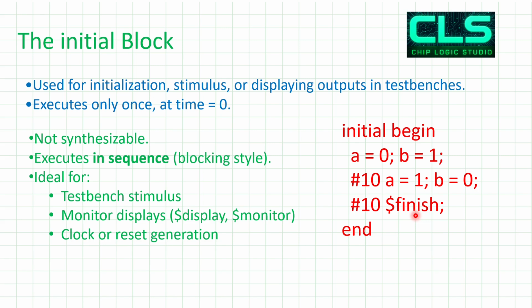After 10 nanoseconds there is no other $finish. So why would we write this in an always block? These are statements we use only in the initial block. We can write them elsewhere, but why should we? That's the question. It is non-synthesizable and executes in sequence in blocking style, because we have used blocking statements.